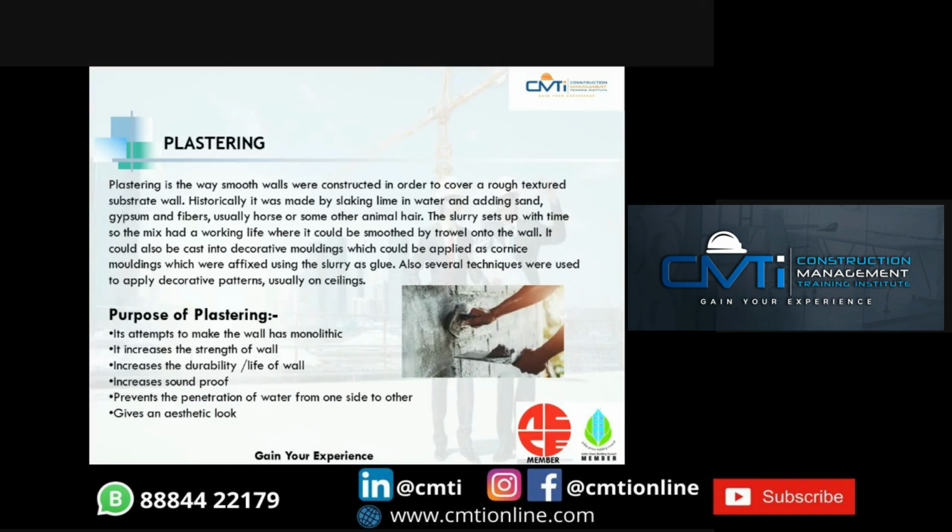So, what is the purpose of plastering? It attempts to make the wall monolithic. It increases the strength of a wall, increases the durability and life of a wall, increases the soundproofing, prevents the penetration of water from one side to the other, and gives an aesthetic look. The different types of plastering are lime plastering, gypsum plastering, and cement plastering. The gypsum plastering does not require any curing and it can only be used in the rooms. The cement plastering can be done in the toilets, kitchen, etc.